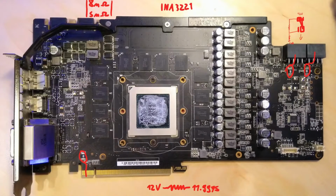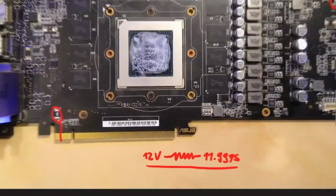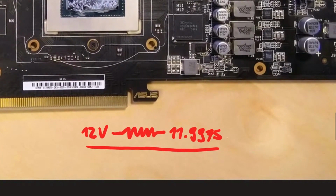On the 20 series it was switched out for two different chips from ON Semiconductor that are NCP somethings. But the way they monitor the power, they work the same. Because they use these shunt resistors and they measure the voltage at the input and the output of that shunt. So we have a diagram down here. And on the left, the power goes in, and on the right, the power goes out.